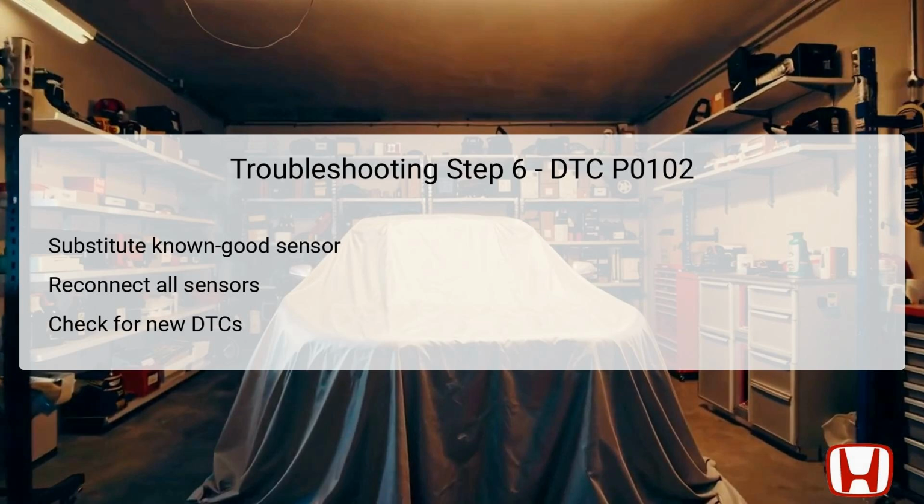While maintaining an engine speed of around 2,000 RPM without any load on the engine, monitor the HDS display for any new pending or confirmed DTCs, specifically looking for DTC P0102. If the code continues to appear, it indicates that MAF IAT sensor is functioning correctly, and further exploration into the PCM may be warranted. If the code does not reappear after clearing it, and if the PCM was previously updated or substituted, the troubleshooting may be deemed complete.